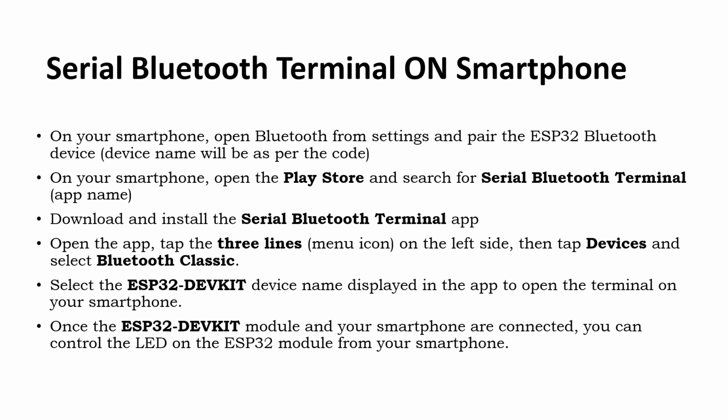So you can change that name also. That name will be displayed in your smartphone. So first, you have to enable the Bluetooth in the smartphone, pair the device, then go to the app, click the device name, then select. So these two things you have to do in your phone itself. But before installing the software, please ensure that the program is compiled and uploaded in the ESP32. After that only you can find the name in that.